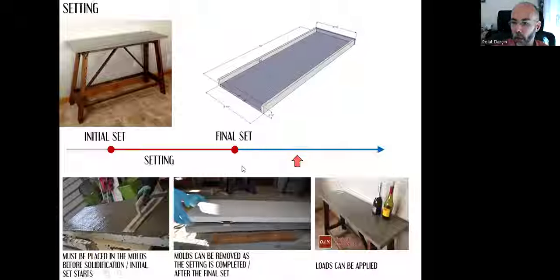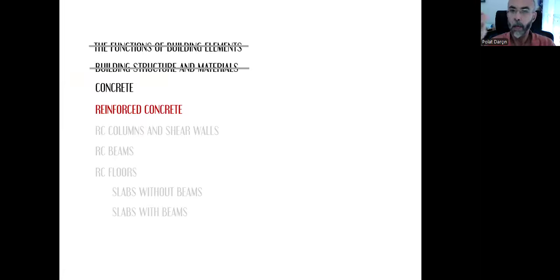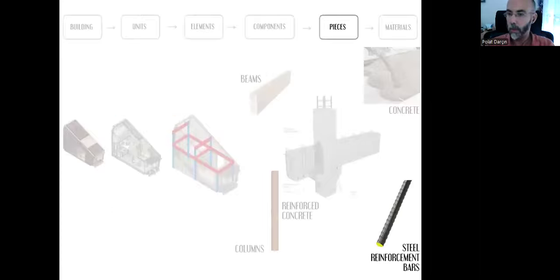If we hurry to apply the loads right after the final set, it can be deformed since it's solid, but not strong enough. So we need extra time so that it will gain some strength to carry all these loads. That's concrete.